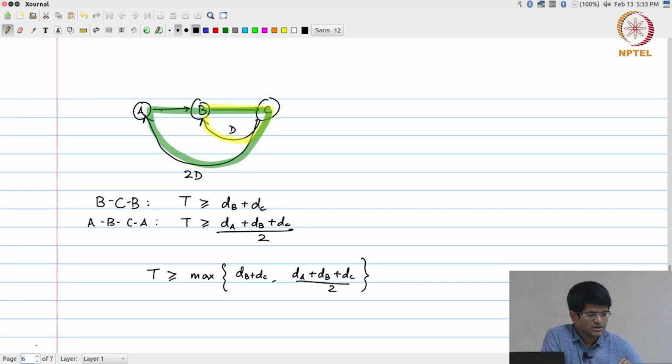Okay. So, like I said, this is the theoretical basis for the best possible performance that I can get out of a given data flow graph under a certain constraint of technology. Keep that in mind. My D values are constrained by technology. So, in other words, if I move to a better technology, 28 nanometers, 20 nanometers and so on, I will probably end up with faster execution units. That itself is sufficient to reduce my value of t, but that is not what we are interested in. Okay. Subject to this constraint of technology, this t is a property of the data flow graph. It is a theoretical minimum bound.